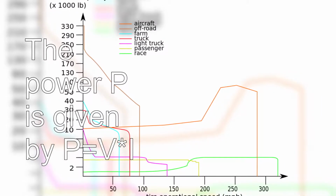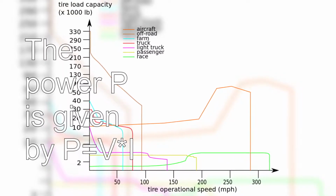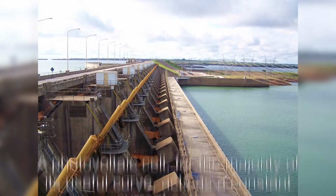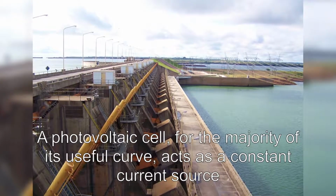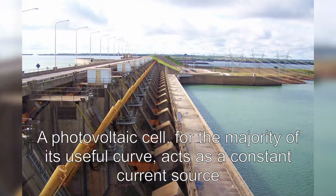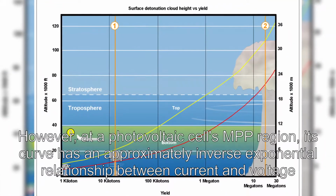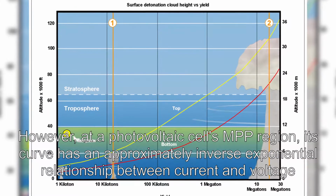In tabulated data, it is often used to estimate the maximum power that a cell can provide with an optimal load under given conditions, P = FF × VOC × ISC. For most purposes, FF, VOC, and ISC are enough information to give a useful approximate model of the electrical behavior of a photovoltaic cell under typical conditions.